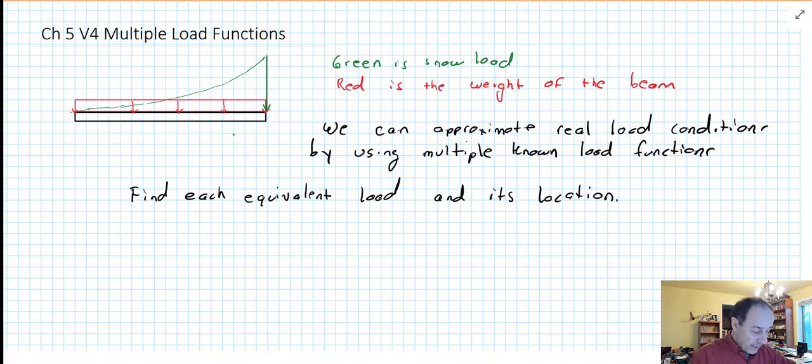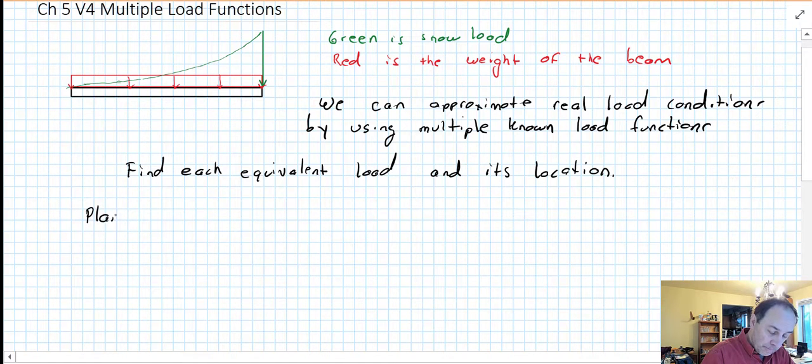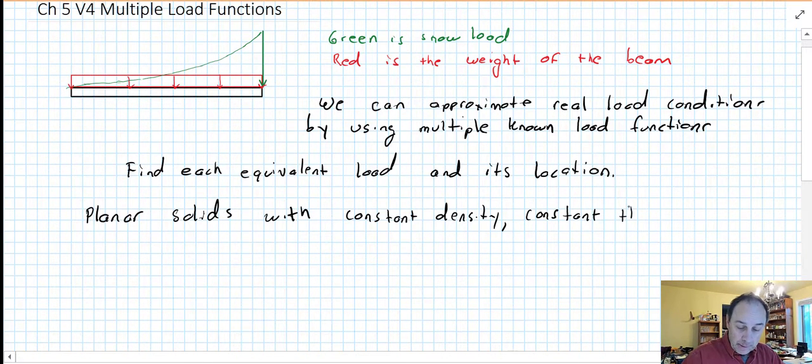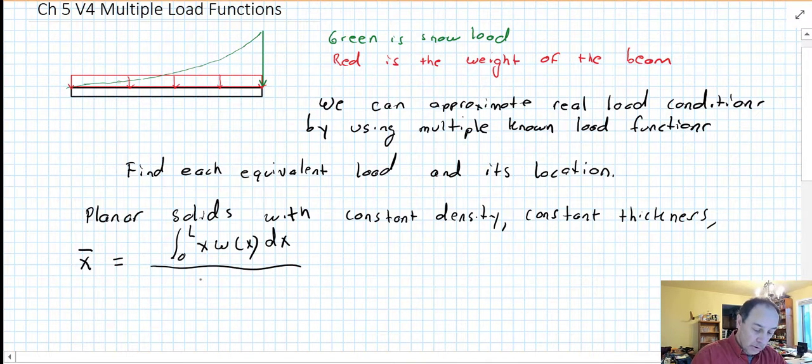So we saw that for planar solids, with constant density and constant thickness, the location in the x direction of that force is the integral from 0 to L of x times the weight distribution function dx, over just the force, which is the same as the numerator with just the weight distribution function, the integral of that. Okay, W of x equals the load curve.